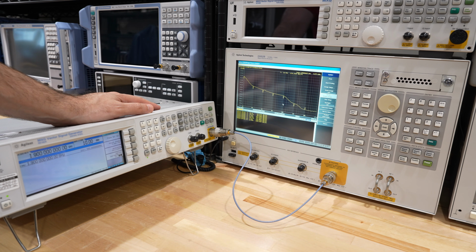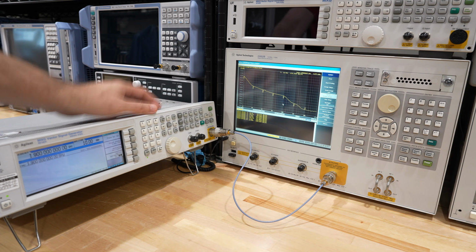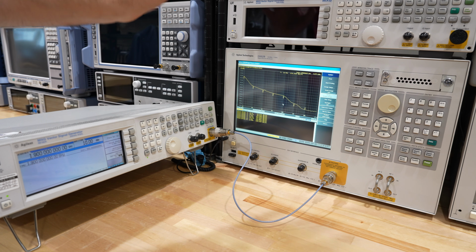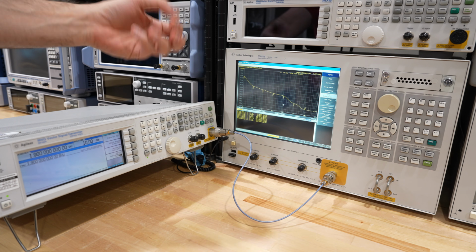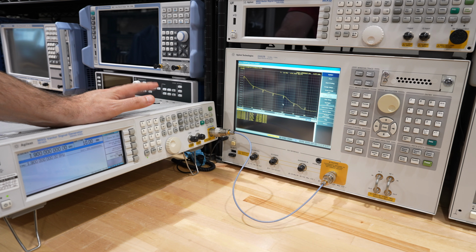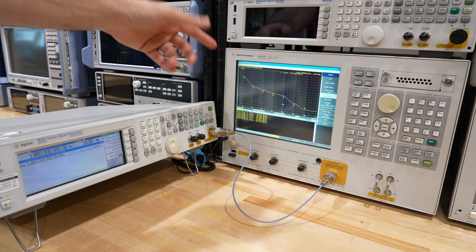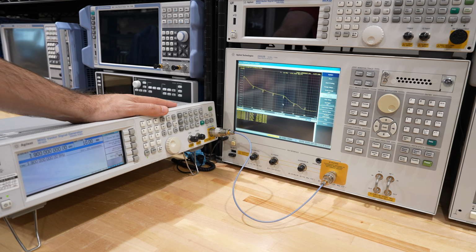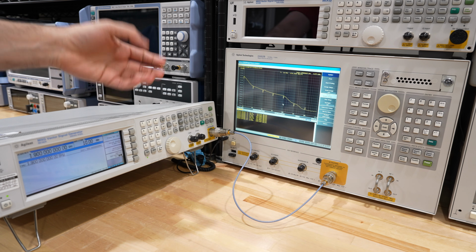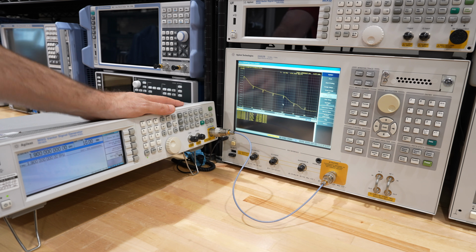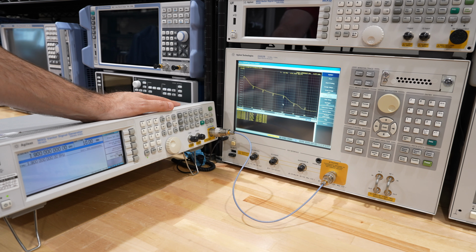We're going to use the Agilent E5052B, which is a cross-correlation signal analyzer. I have a complete video on what cross-correlation means and how phase noise measurement is actually done, so definitely check that out. And we have a plot over there, and we can compare that with a plot of a data sheet of this model. I couldn't find exactly the year because this is a fairly old model, but nonetheless, it should be pretty close to what this data sheet says.